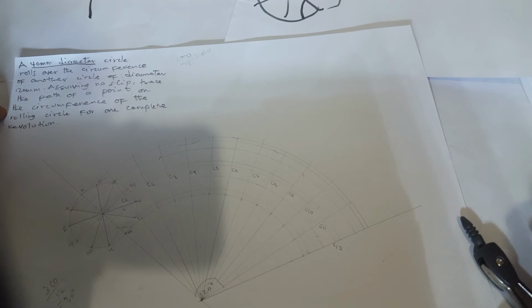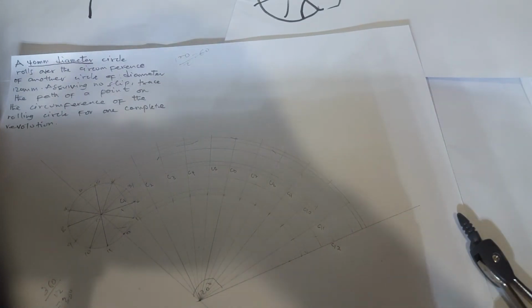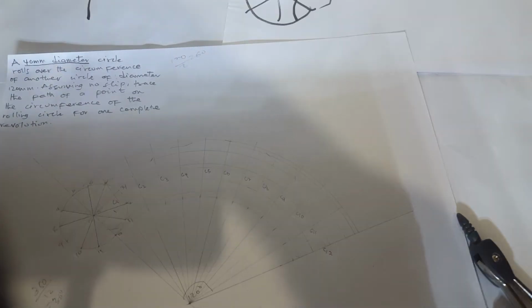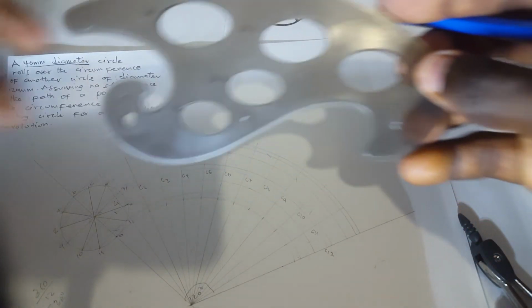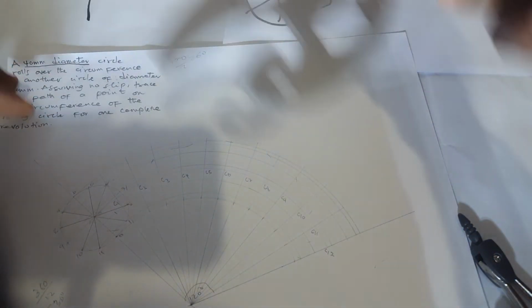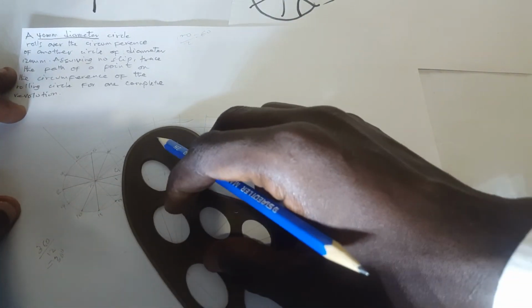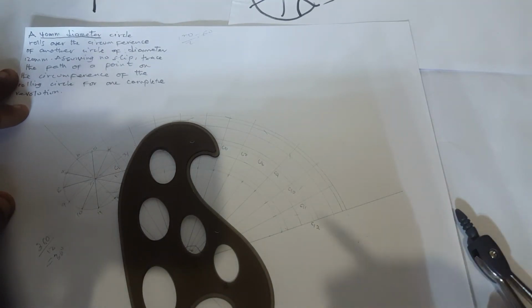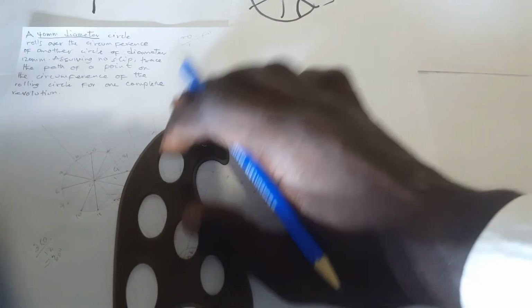Now the only thing you do is that you take your French curves. So let's get our French curves, and then we draw the curve through that. Okay, good. This is what we call the French curves. So it's easy to join all the points we've drawn, but we have to do that carefully. We join one point to another, or if all the points fall in line, we can join 3 points together. But we don't use our hands to do that.